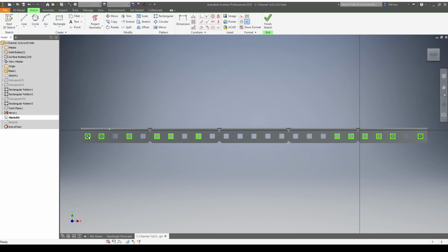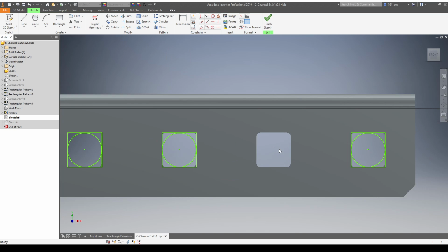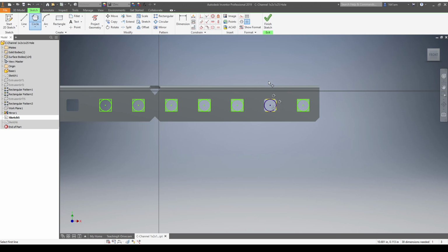So now since I know I had the two holes next to each other on the other side, I know that this side is the one I have to constrain. So let's go down to it, project geometry, click three of the edges, click tangent circle, and then you get the circle that you need.